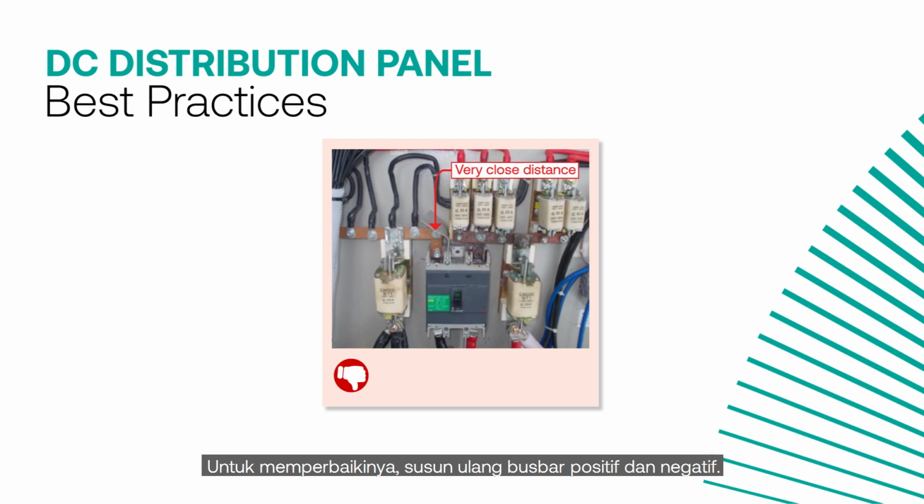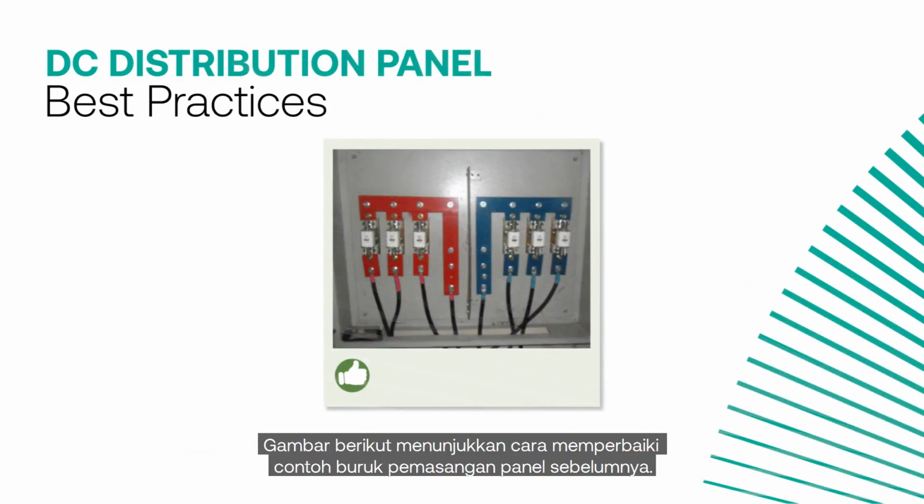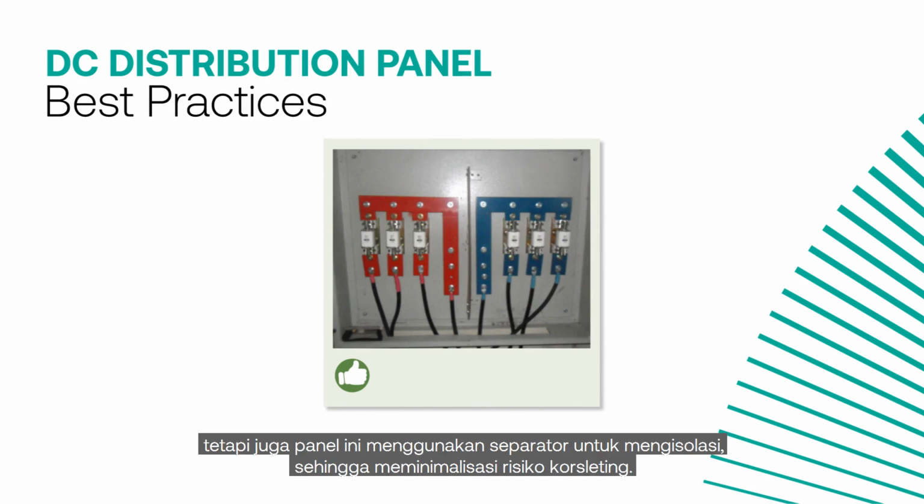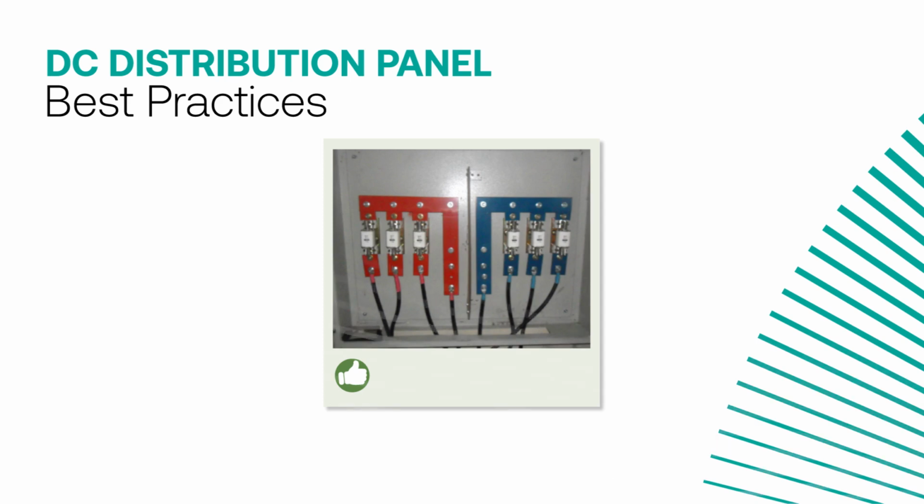To fix this, rearrange the positive and negative busbar. The picture shows how to fix previous bad example of panel installation. Not only that the positive and negative busbar have adequate space, but this panel also uses separator to isolate and to minimize the risk of short circuit.